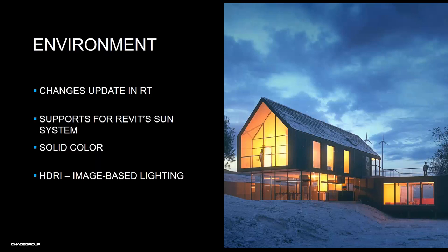For the environment lighting, you can use the daylight system in Revit with V-Ray Sun and Sky system, or you can use one light source called dome light. It's a hemisphere or full sphere light. You can feed it with a 360-degree image and light you're seeing.